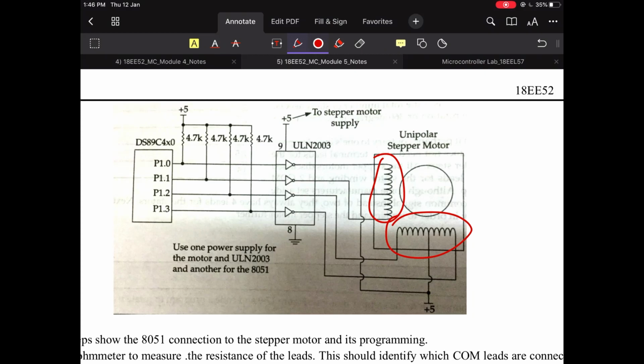I need a stepper motor power supply or a driver circuit. Why? The voltage requirements are different from those of your microcontroller. I am using 4 pins from the microcontroller to energize the stator part. I will send different sequences, say 1, 0, 0, 0, and it rotates. Later I will send 0, 1, 0, 0 and it rotates.